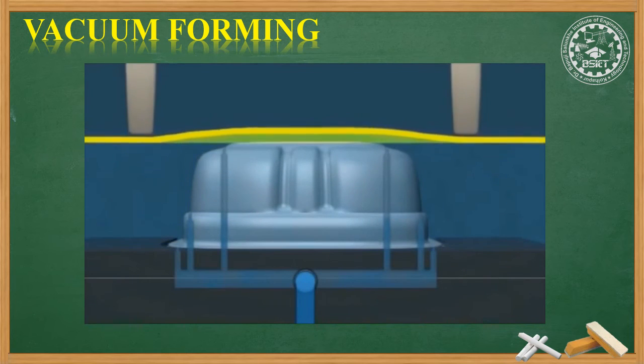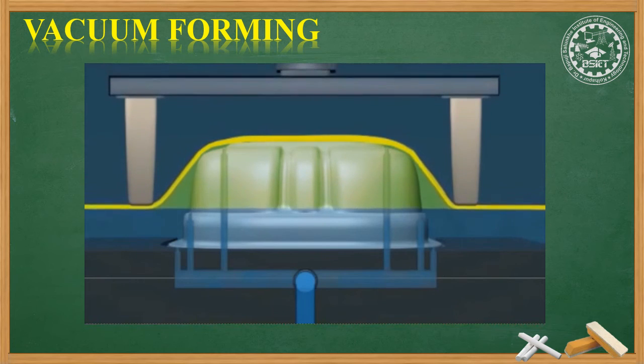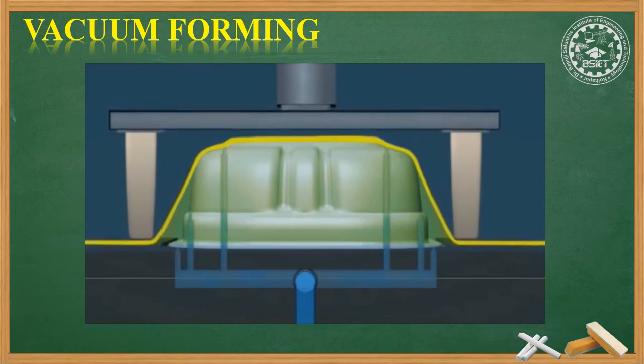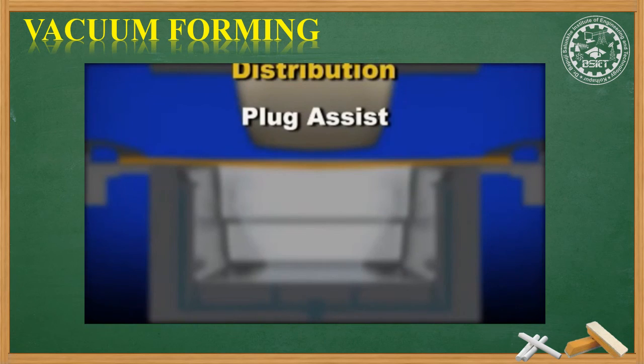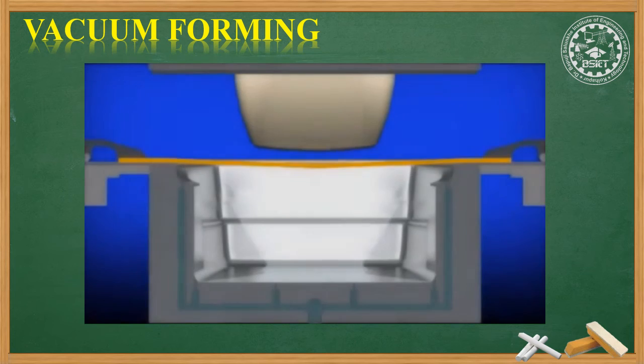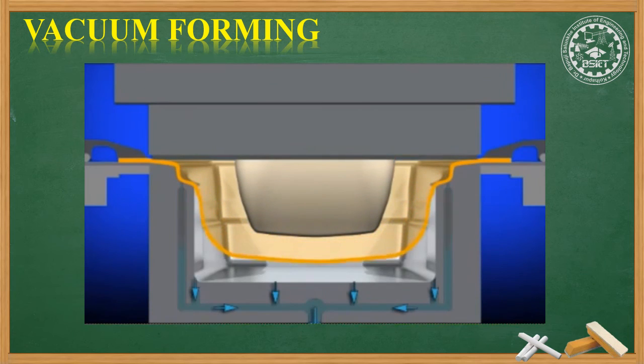Drape thermoforming is where plastic sheet is draped over a male mold. The sheet stretches as it is pulled. Another way to stretch the sheet into a deep section is called plug assist. In fixed plug assist, a plug is attached to the upper half of the mold. The mold closes and the plug stretches the sheet. A vacuum then pulls the sheet onto the surface of the mold.